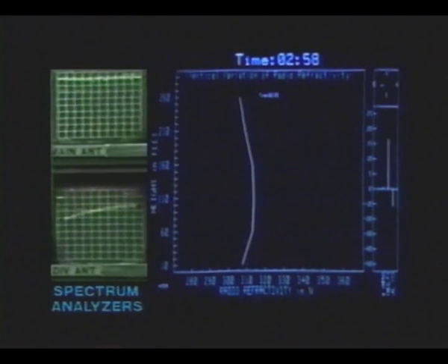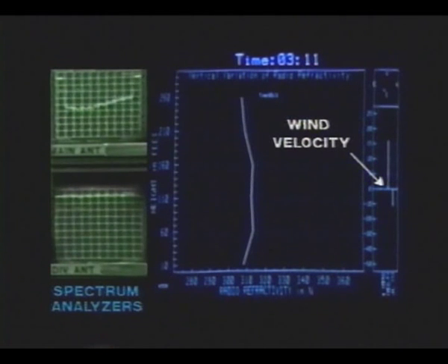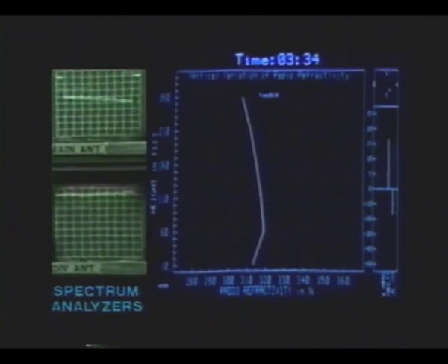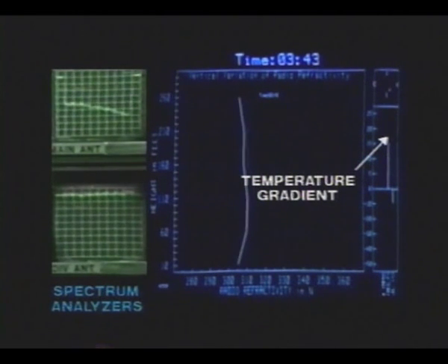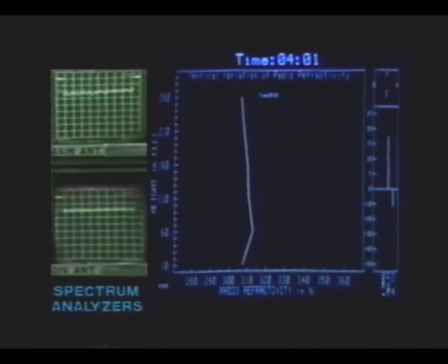From 3 to 3:30, the wind velocity slows to 0 miles per hour and remains there for over an hour. At this time, the main receiver experiences a 25 dB flat fade accompanied by a 30 dB notch, which gives a composite fade greater than 55 dB. At 3:30, the temperature gradient begins to grow significantly, and the refractivity begins to become more negative. The main antenna experiences a notch and flat fade, which combine to produce a total fade which reaches minus 80 dBm.